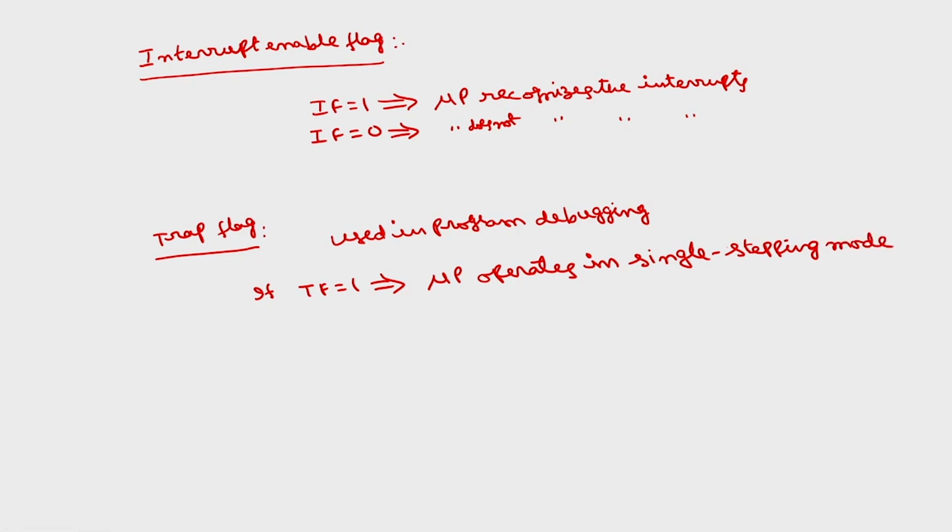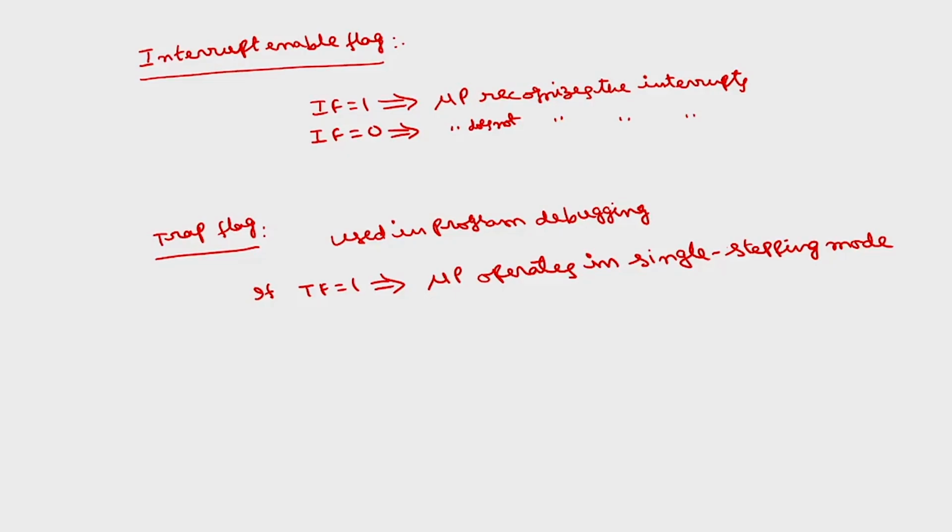That is, after each instruction is executed, the microprocessor basically will be interrupted. So, at the interrupt service subroutine, you can write the program to display the contents of the registers and memory locations. Say for example, if you have instructions like MOV AL, BL, INC CL, LEA with some 6000H, some sort of instructions, I will describe the instructions later.